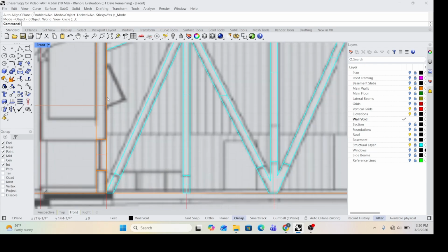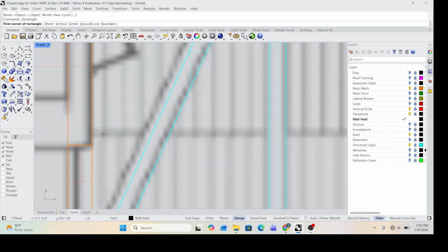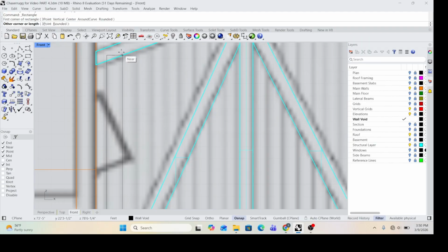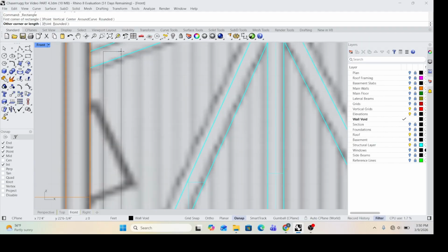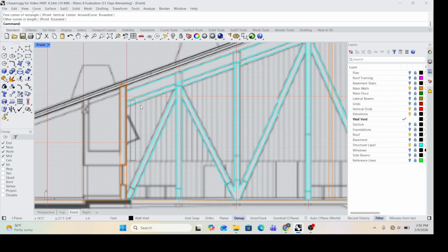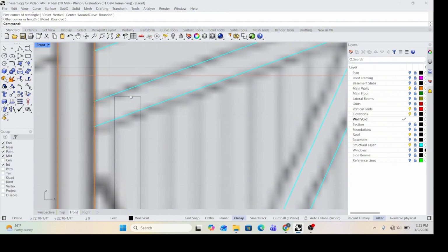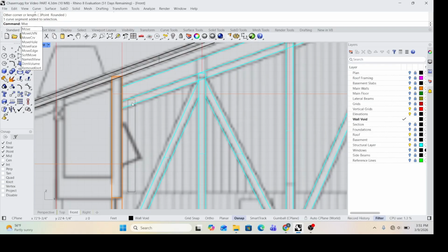And then we're going to use a new tool called Array. So I'm just going to come into my rectangle. I'm going to kind of guesstimate here based on the drawing. And I'm actually going to stop it early, because if I go too far up, I start drifting this way. So I'm going to stop here. And now that I have the width I want, I'm going to hold Control Shift. I'm going to pick this line. I'm going to say move.